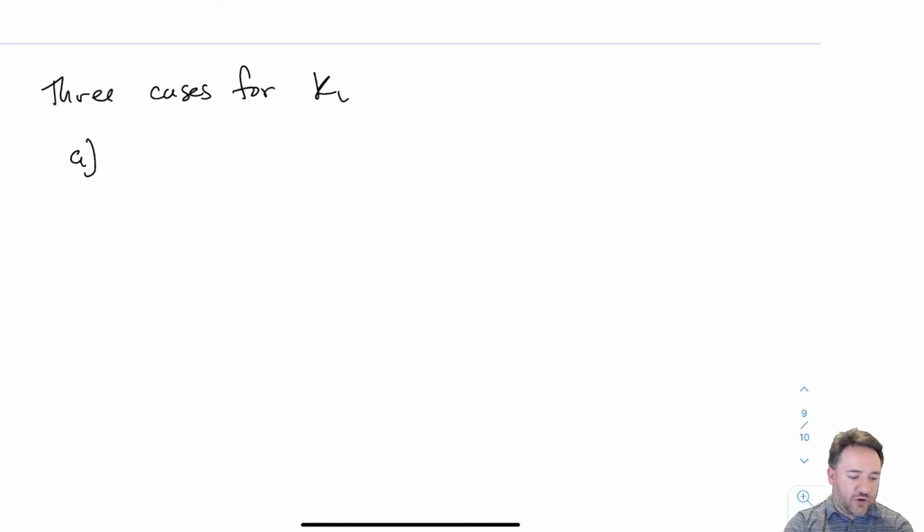And then I have a third regime for KL, which is where I have basically pure elastic lateral torsional buckling, which looks like this. My ruler here is having pure elastic lateral torsional buckling. That means it buckles, but then nothing happens to the material. Everything remains elastic so that when I let it go, it just comes back. Those are where I'm going to get the highest reductions for KL, but I'm not getting any inelastic thing happening. So each of those different cases has a different calculation for KL.